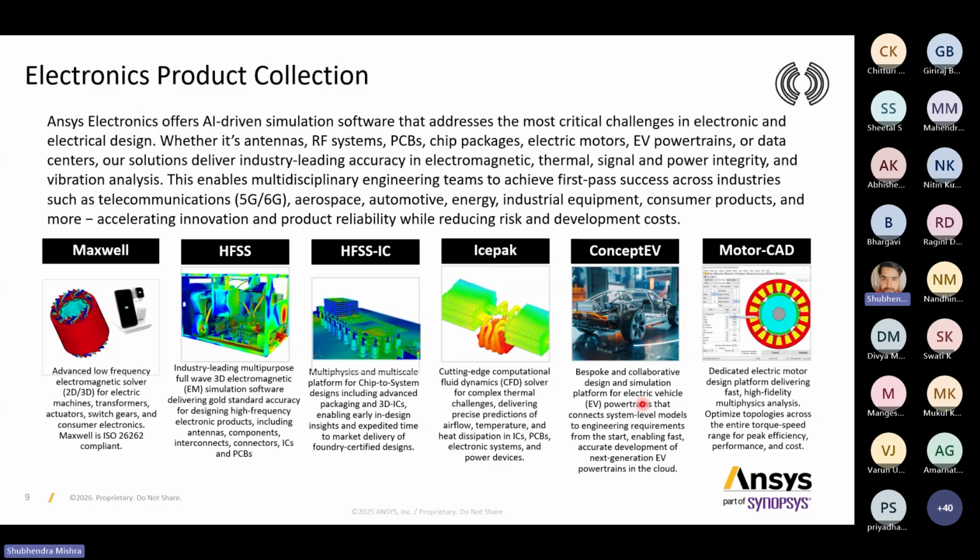We have Icepak, which is a dedicated tool for thermal analysis. After completing your electromagnetic simulations, you will move to thermal analysis, which we call electrothermal analysis. When you complete the electromagnetic simulations, you import that design here and proceed with the simulations. You can analyze the temperature, the airflow, the surface current density you want to plot, how the fan is reacting, and all heat dissipation. All things are possible in Icepak itself.